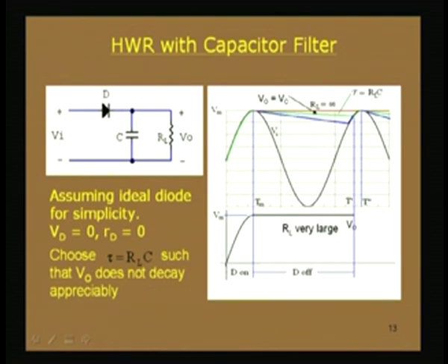So from the peak value it is falling off. The capacitance has already charged to the peak value Vm, but after this peak point, input voltage Vi is going down. If we consider the diode, on the cathode the capacitor voltage is applied and the anode is the input voltage.